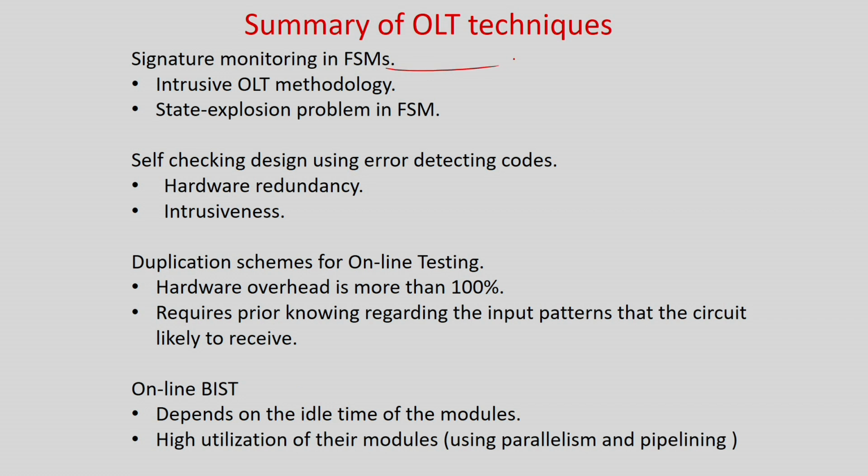We have seen first that signature monitoring in FSMs is an intrusive methodology, and also has the state explosion problem. Then we have seen error detecting codes. The good advantage of error detecting codes is that the area is very low, but again it's a very intrusive design. You have to change the circuit entirely. So people started looking at duplication based online testing schemes.